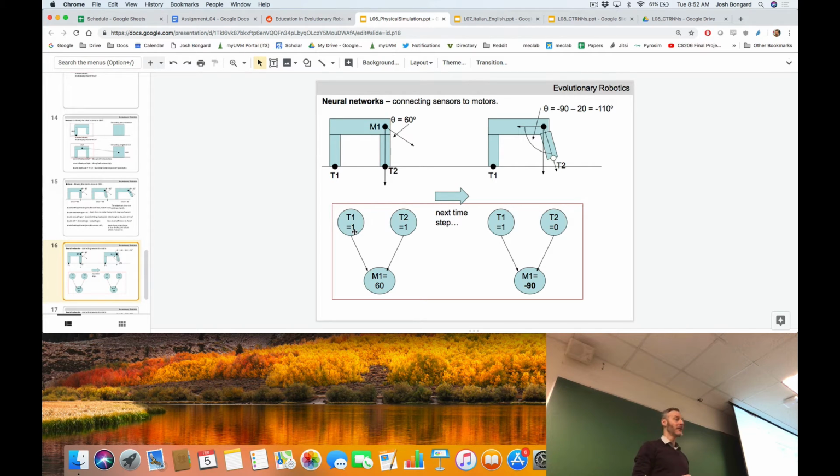The robot starts moving. In assignment 4 now, when you add sensors and neurons, you're going to see exactly that. With your scissor bot, which is not too different from the robot you see here, just these two pieces, you can actually get forward scissoring locomotion with something that is as simple as the Braitenberg vehicle. There's no sine function in here. There's no sine wave. There's no oscillatory pattern embedded in the neural network. That oscillatory pattern is arising from this embodied loop, right? Sensation, action, interaction with the environment, changed sensation, changed action, and around we go.